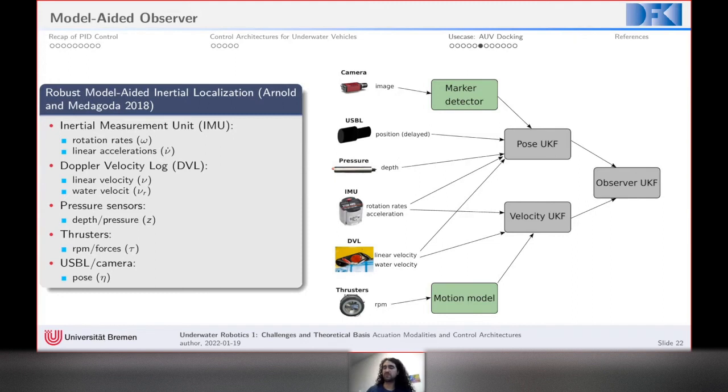The same kind of device, you can also operate in another way, which is called acoustic Doppler current profiling, or ADCP mode. What you're trying to measure here is not the strong reflection from a solid ground, but the small reflections from backscatter in the water.